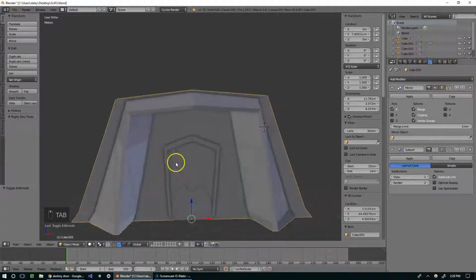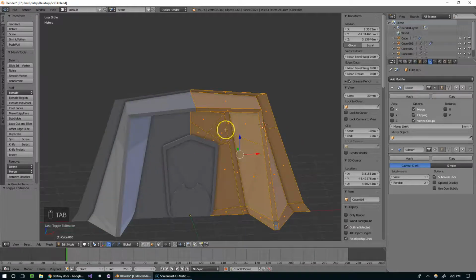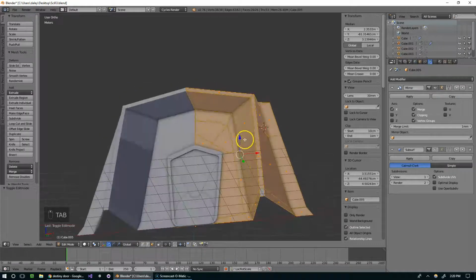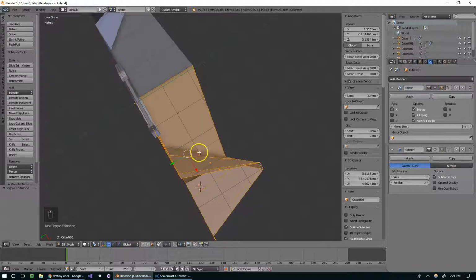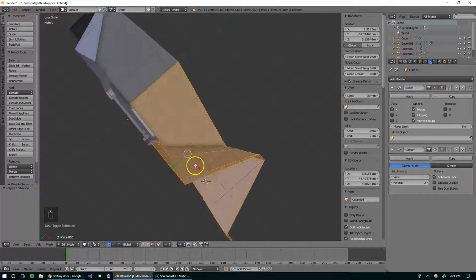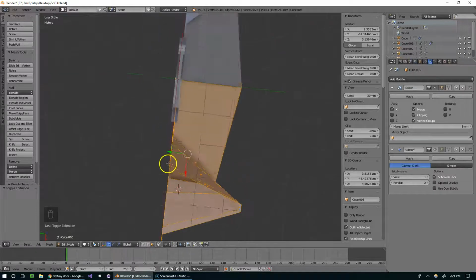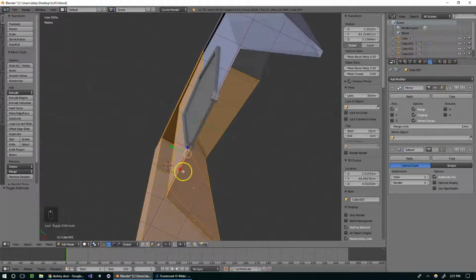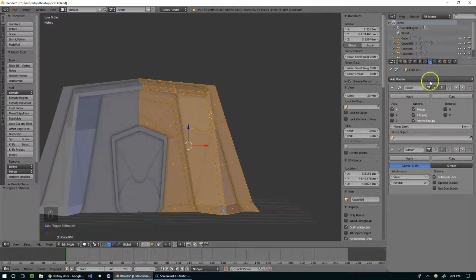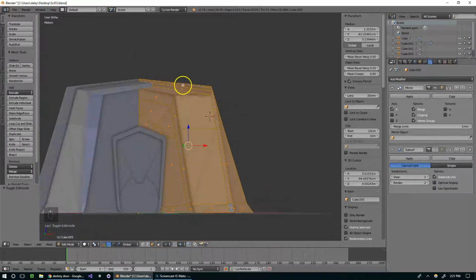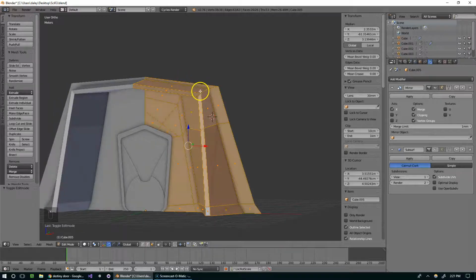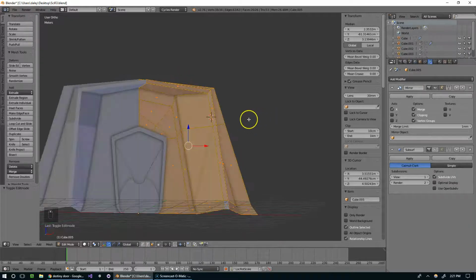And it's having trouble shading these faces now because I created non-planar geometry. Essentially, every face needs to be a perfectly flat plane. And you can see from certain angles, this plane is obviously being warped in the middle. So there's a few ways we can fix that. Typically, the best way is to just not do that in the first place.